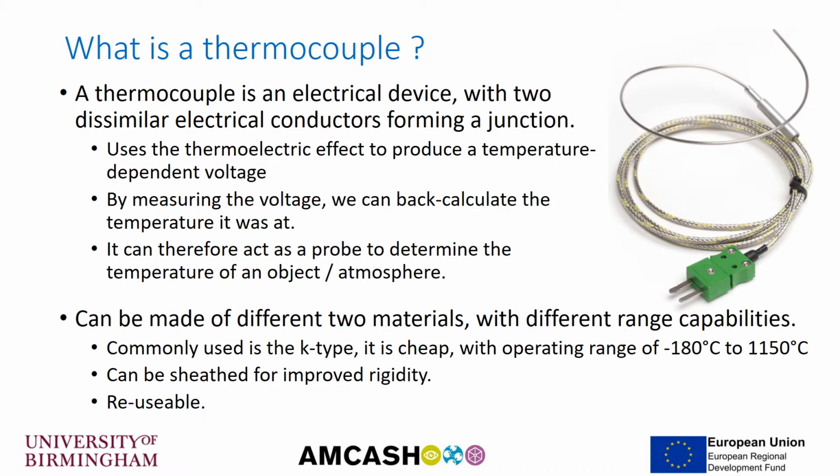Well, it's an electrical device with two dissimilar electrical conductors inside it that form an electric junction. It uses the thermoelectric effect to produce a temperature-dependent voltage. And if we measure that voltage and we know the temperature dependency of the materials in the thermocouple, then we can back calculate the temperature that it was at. It can therefore act as a probe to determine the temperature of an object or an atmosphere that it's in